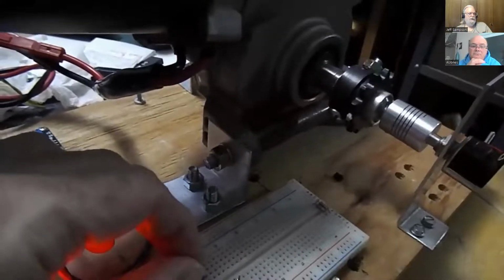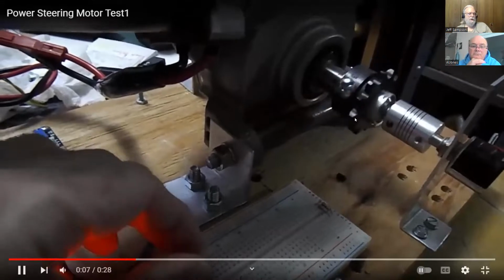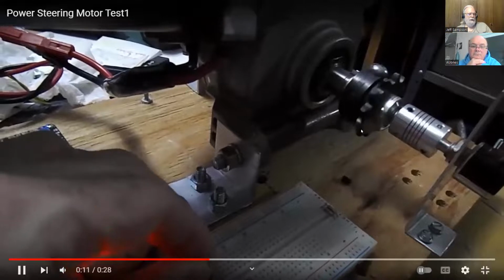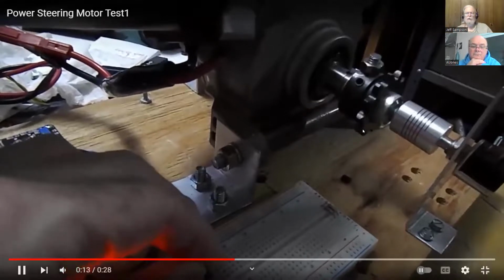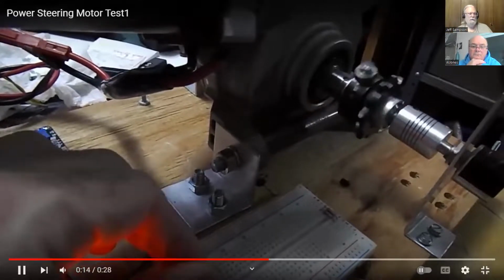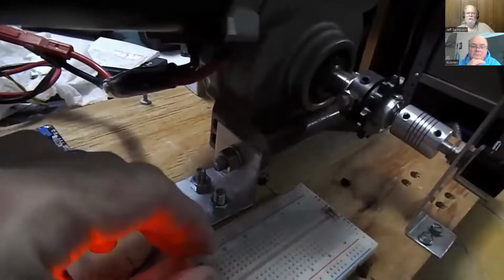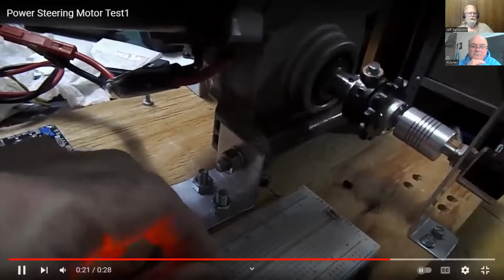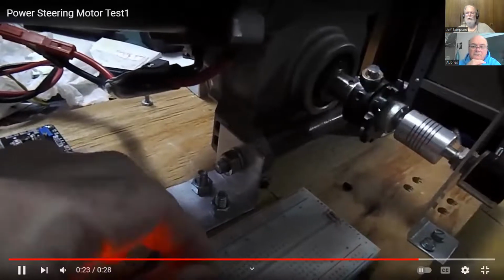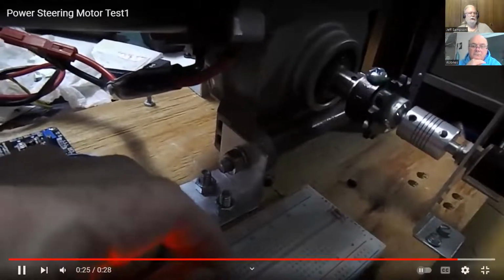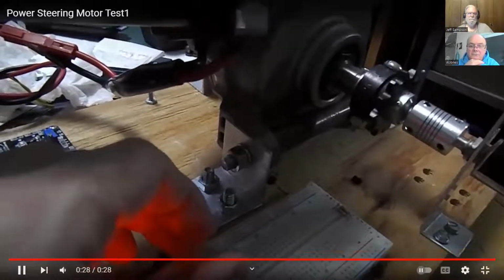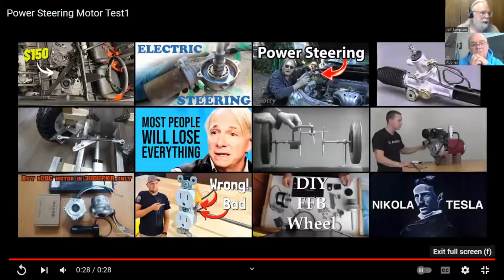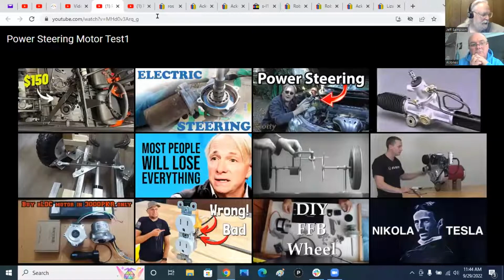If you're listening to the audio, you can hear it. When I go too far, you can hear the motor shuts off completely. And then when I move it slowly, it tracks, and the motor's whining because I haven't put in that other output routine. You can make the motor completely quiet if you use the Timer1 library as opposed to a regular analog write. I don't remember what you're using there. So here, let me grab these and post this one.